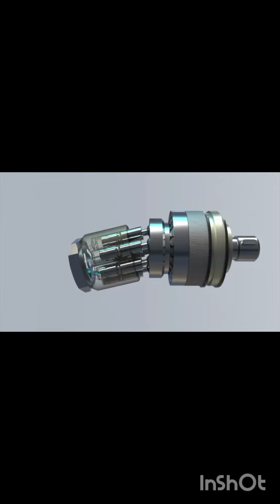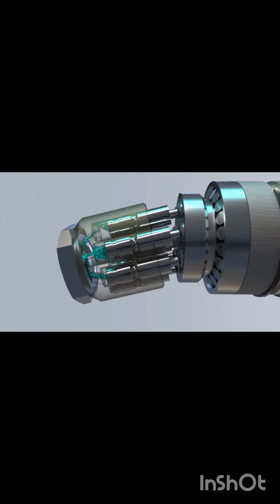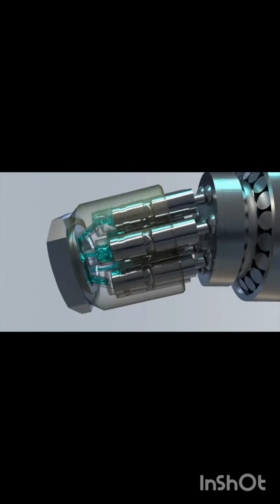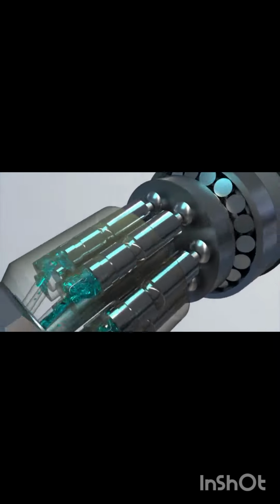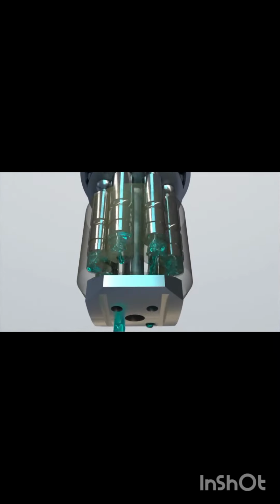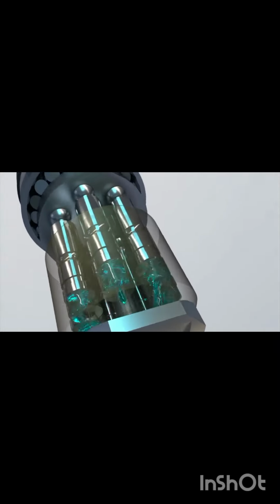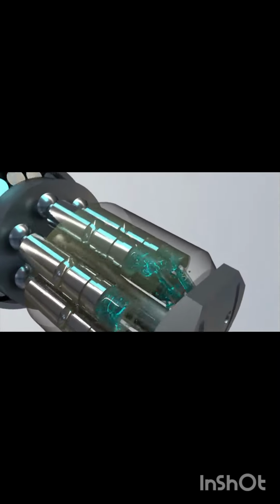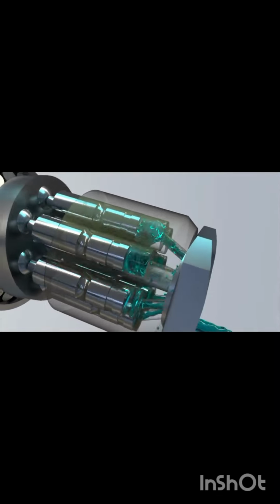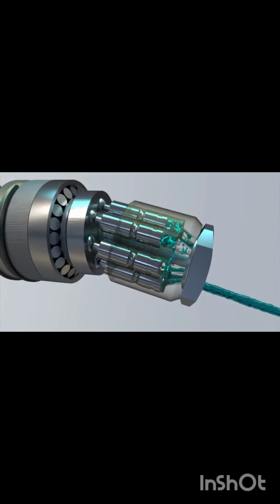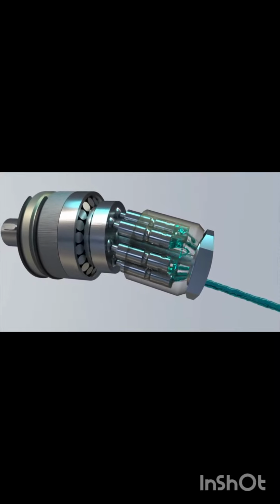Several pistons are installed in the pump housing. There are 7 in the example provided. While one piston performs suction, the other is pushing the fluid into the pressure line, and the third is in the extreme position. This design allows for a continuous supply of fluid with relatively low pulsations. The presented pump does not need any check valves since its pistons always suck in one area and discharge in another. The design of swash plate pumps is different, but the principle of their operation is the same.